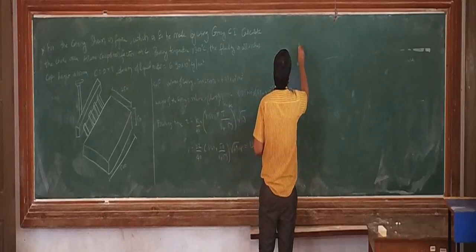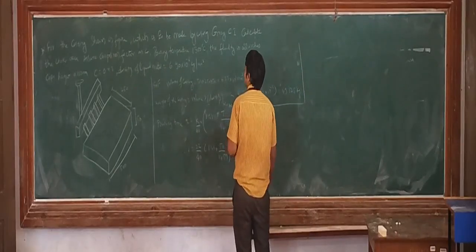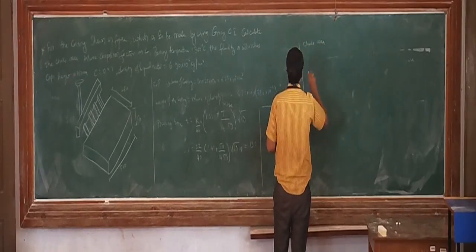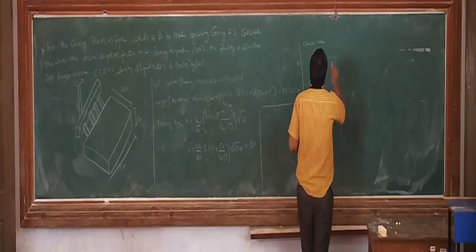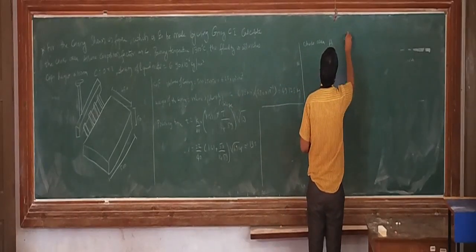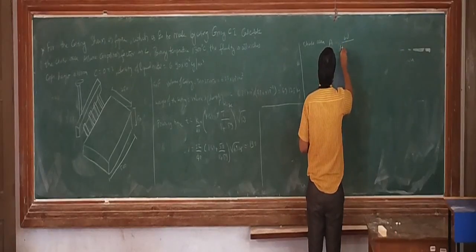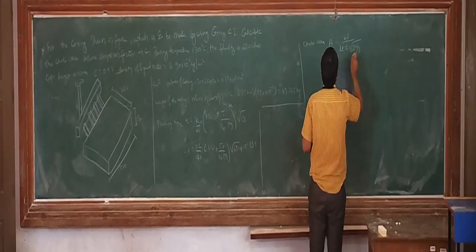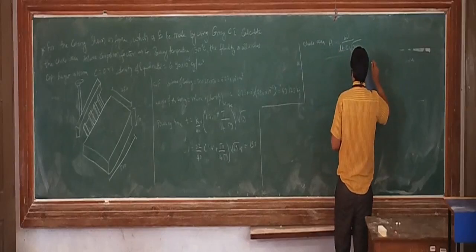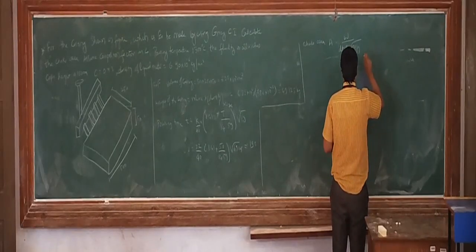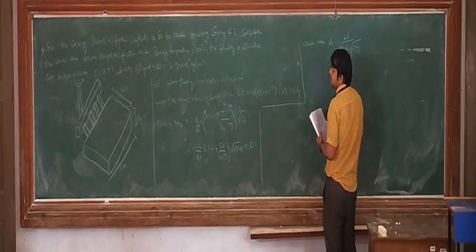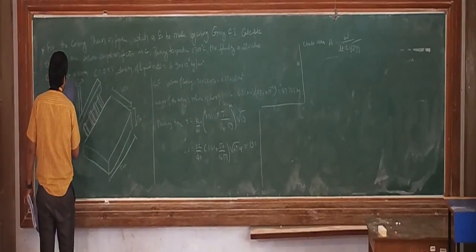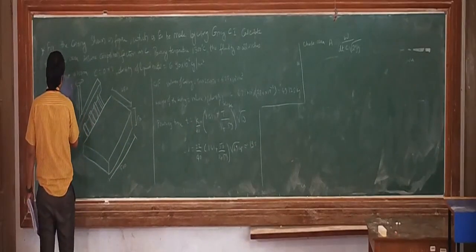Okay. Then we have choke area. A is equal to W divided by D T C into square root of 2GH. Okay. So here H is the effective sprue height. So here sprue base is not visible, so directly this height is taken. This height is also given as 100. Okay.